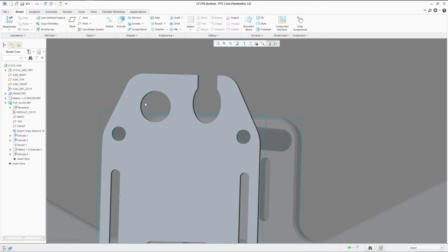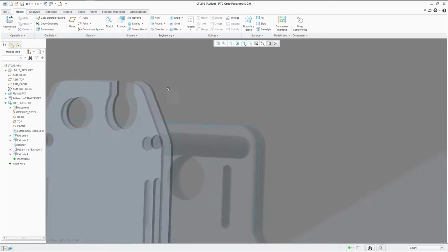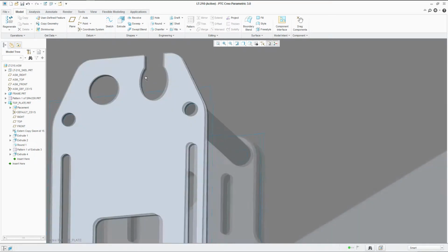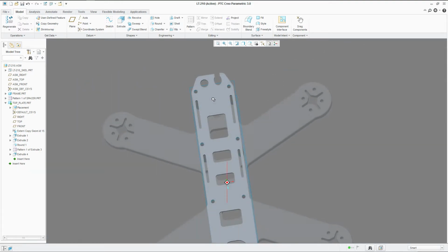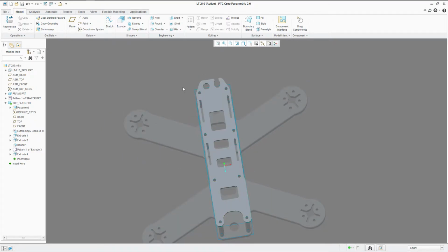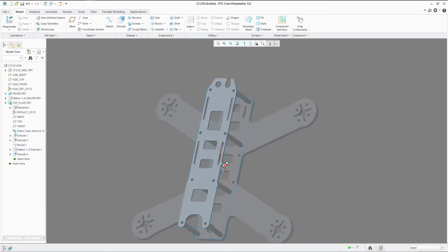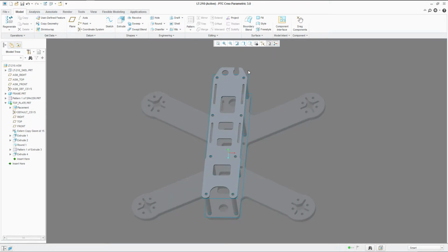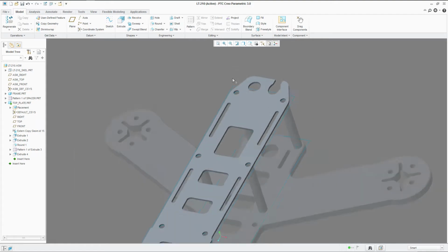Something like this. You can screw your VTX antenna in and hang your battery leads with your XT60 connector. Whatever you like, you can make it. Some have it on the side here. I'm also not a fan of having it close to the video transmitter or antenna for interference.